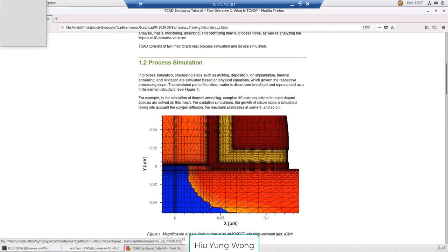In E128, you learn that you have, let's say, a PN junction. How do you form that? You do that by introducing some impurity, for example boron or phosphorus, into it. But you need to control it. How much do you want to introduce, 1E18, 1E19, and how deep do you want to introduce? And how do you do that? You use ion implantation or diffusion. And all this relies on physics.